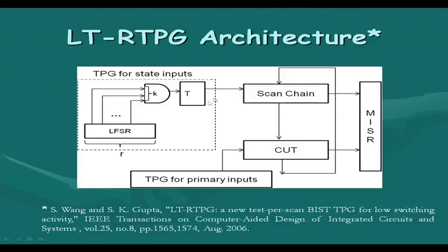Ideally we should take, say, the LSB of the LFSR and connect it serially to the scan chain. Whenever this LSB switches, a scan transition is introduced, and when a number of bits have been shifted into the scan chain, that is the test pattern.